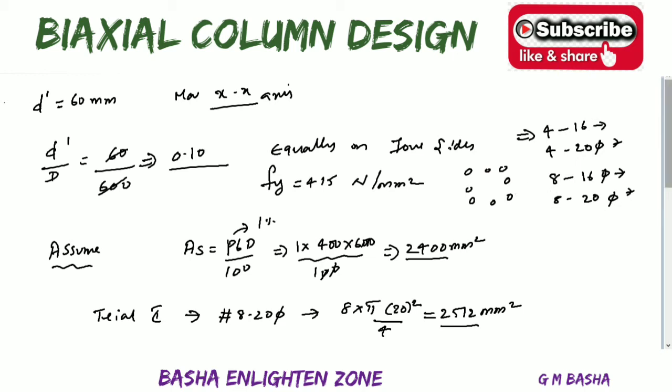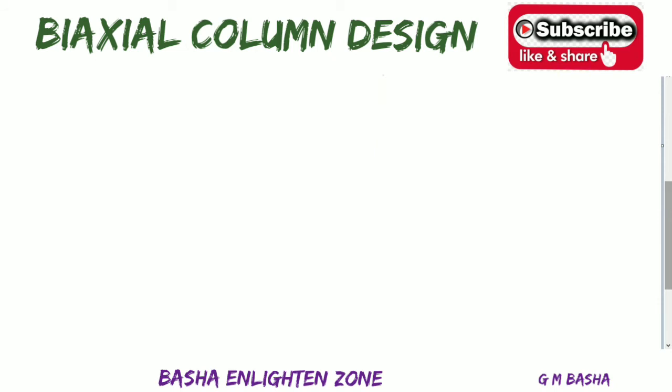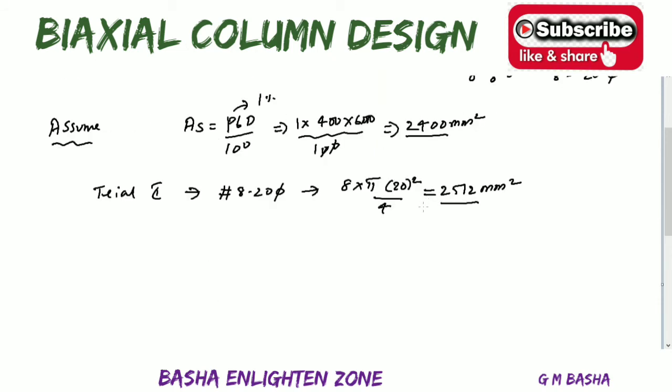Then according to this condition, provide 8 bars of 20 dia. Therefore your area of the steel will be equal to 2512 mm square. Relate this using the formula: 2512 equal to, here p is your unknown, p by 100 into 400 into 600.